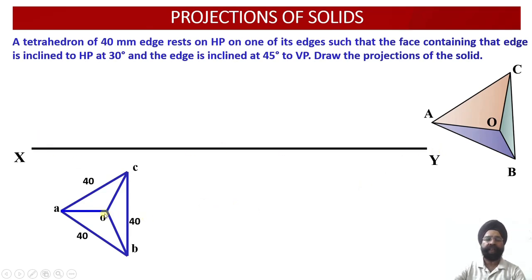Having located this axis point and drawn the slant edges using object lines, now we have to draw the front view of this. So this is my axis point. Through this I am going to draw the axis line to work out my front view.